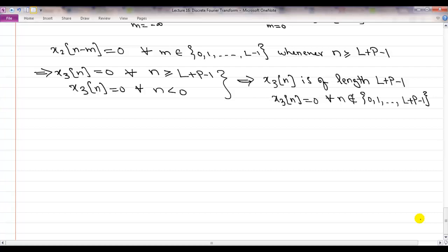Now, let's figure out what does circular convolution mean in terms of sampling of the frequencies of the sequence corresponding to the linear convolution. Okay? Remember that we talked about sampling, the way we derived the DFT. Before that, we had a small section where we talked about sampling the DTFT of a sequence. And we'll try to exploit that.